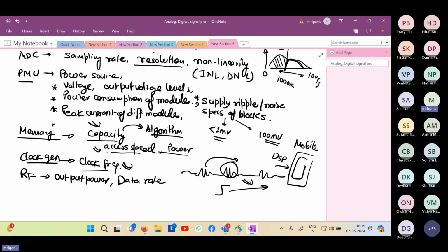But some computer science person has come up with an algorithm, and without understanding the hardware constraint, his algorithm requires too much processing power, too much memory. In that case, it will end up burning too much power for the computing. It will require too much memory for the computing. So then it will not be suitable for deployment on the chip. So if you have to save this RF power and justify putting DSP on the chip, it has to be a simplified or low power DSP algorithm. Compute effort has to be less. It has to be a relatively lightweight DSP algorithm.